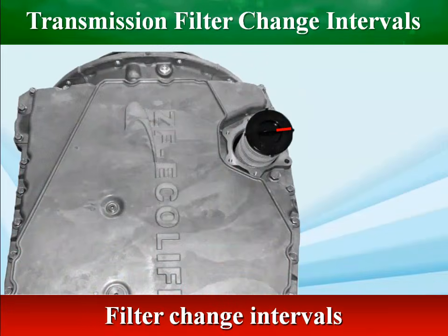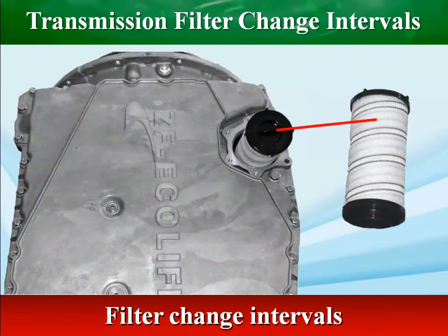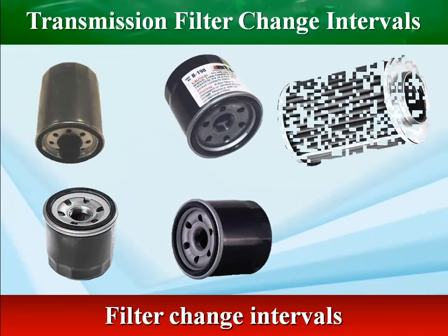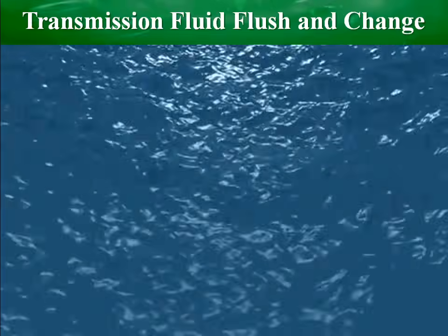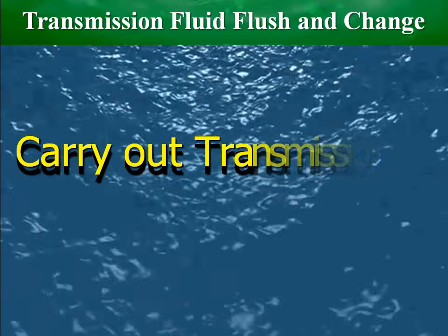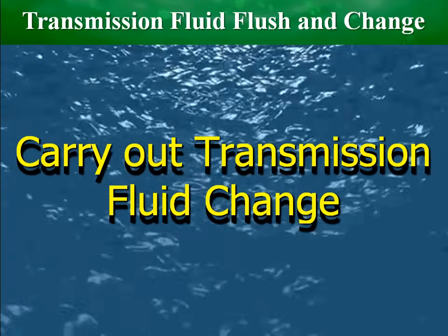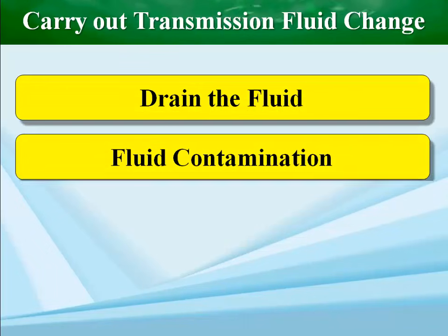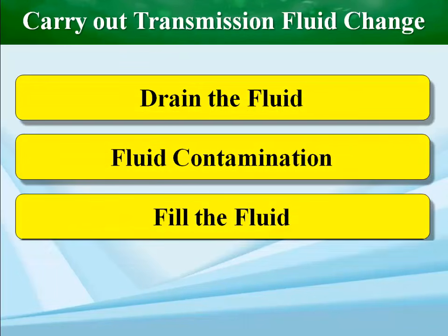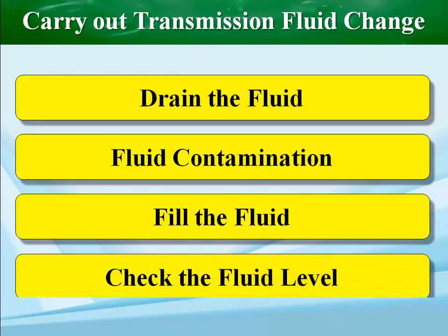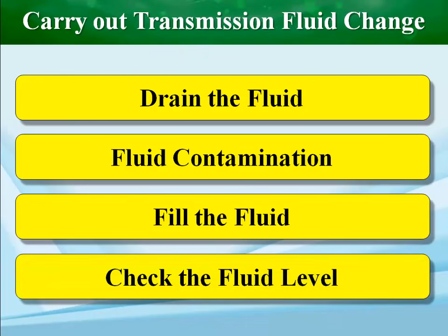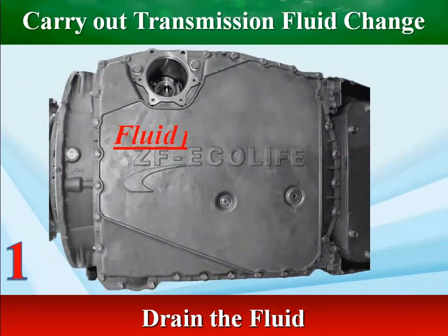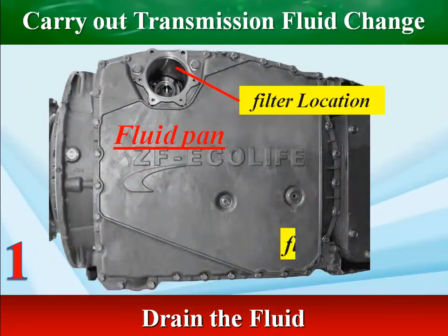The filter must be replaced each time the fluid is changed. A transmission fluid change involves draining the old transmission fluid from the pan, replacing the filter, and refilling with new fluid. Only drain ATF at operating temperature and for at least 10 minutes.